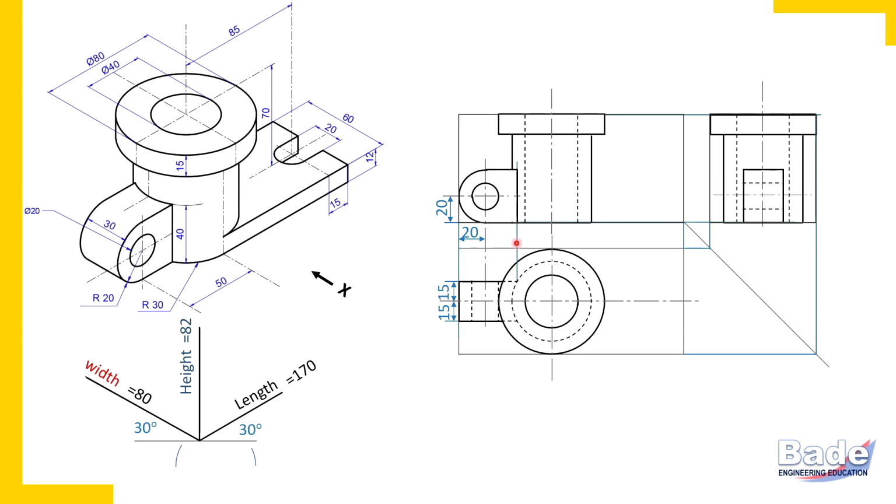So this is how the U-shaped block is complete in all three views. Now let's focus on the plate. Its largest surface appears in the top view, and in the front view and in the side view it appears as a rectangular strip as usual. So let's focus on this plate in the top view.